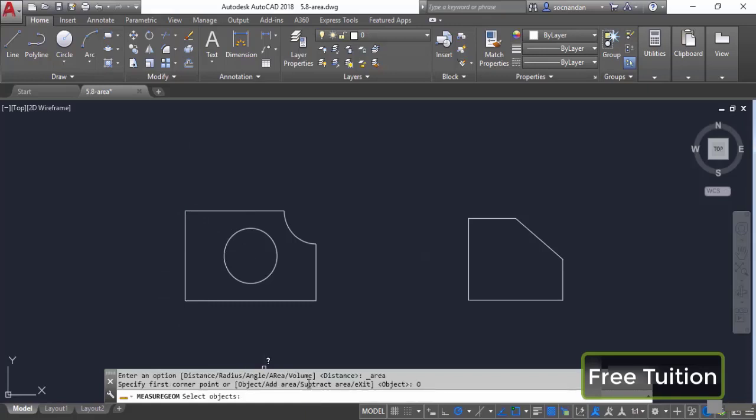Now click on it and simply click on the object. For clicking on this object, you need to ensure that this complete object is made with a single unit, a single polyline or region, and it should be connected, because you cannot use this tool for finding the area of this geometry. In this case obviously we have these connected lines, but this line is not connected and hence we won't be able to find the area in this case. So simply click on this geometry and the complete area is selected including the circle.